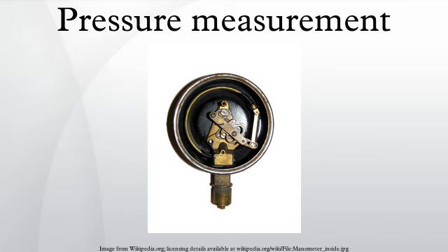Mechanical details. Stationary parts. A. Receiver block. This joins the inlet pipe to the fixed end of the Bourdon tube and secures the chassis plate. The two holes receive screws that secure the case. B. Chassis plate. The face card is attached to this. It contains bearing holes for the axles. C. Secondary chassis plate. It supports the outer ends of the axles. D. Posts to join and space the two chassis plates.